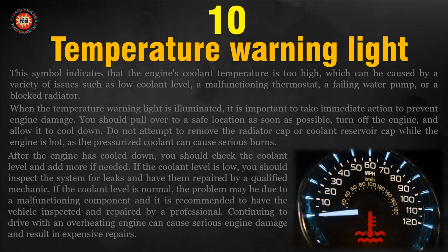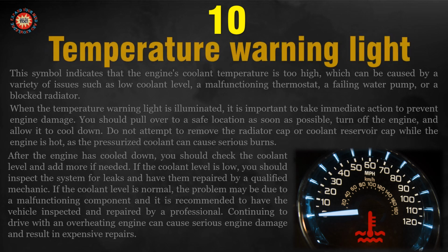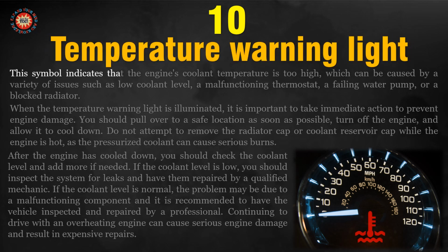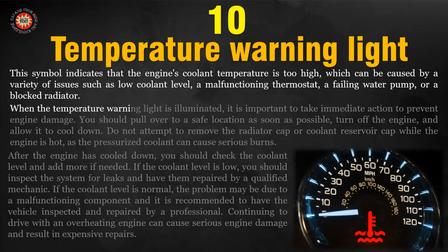Symbol 10. Temperature warning light. This symbol indicates that the engine's coolant temperature is too high, which can be caused by a variety of issues such as low coolant level, a malfunctioning thermostat, a failing water pump, or a blocked radiator. When the temperature warning light is illuminated, it is important to take immediate action to prevent engine damage.